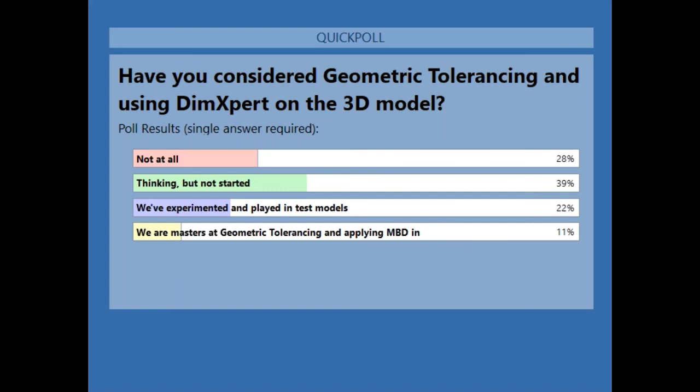On a GOM system, absolutely what David has shown, a lot of the measurement happens on the exterior surface geometry. So for things that are deep inside of a part, whether it be 1 inch or 2 inch, most GOM systems also come with a probe.